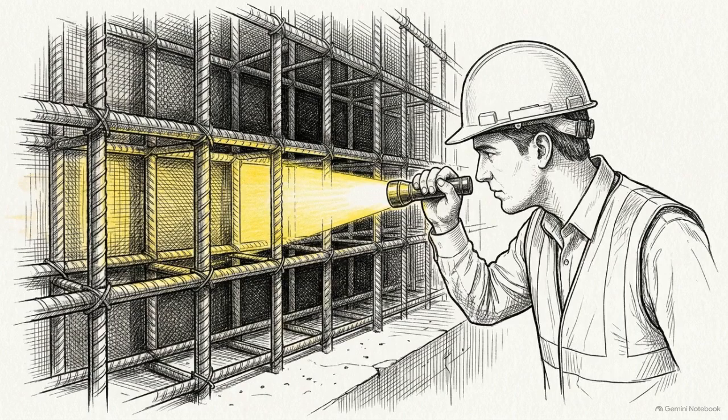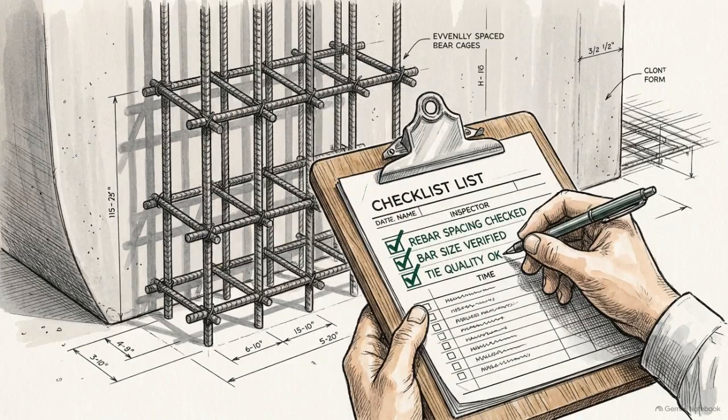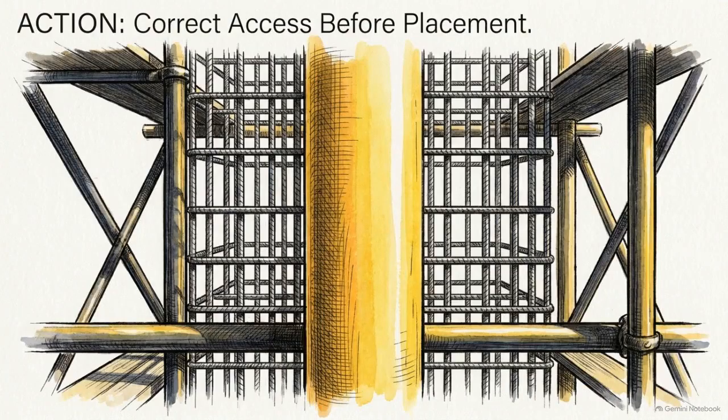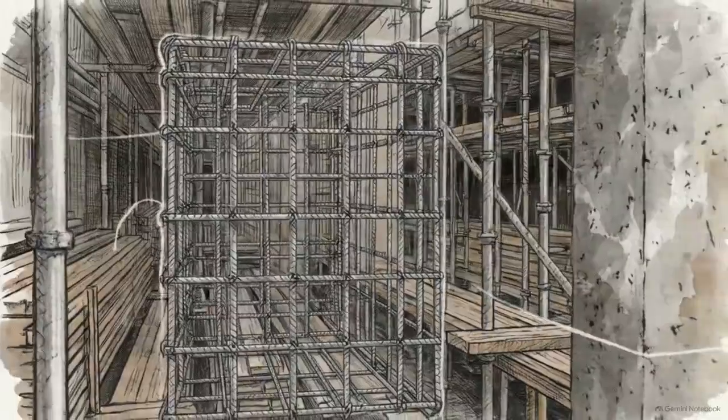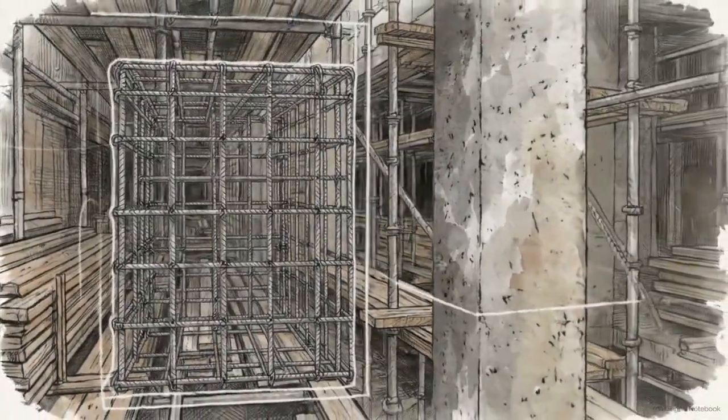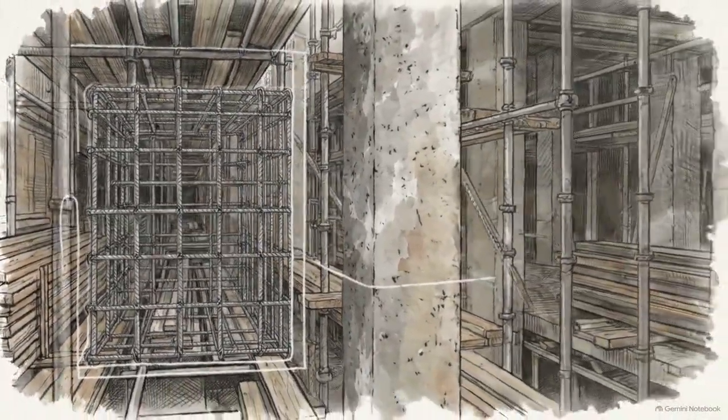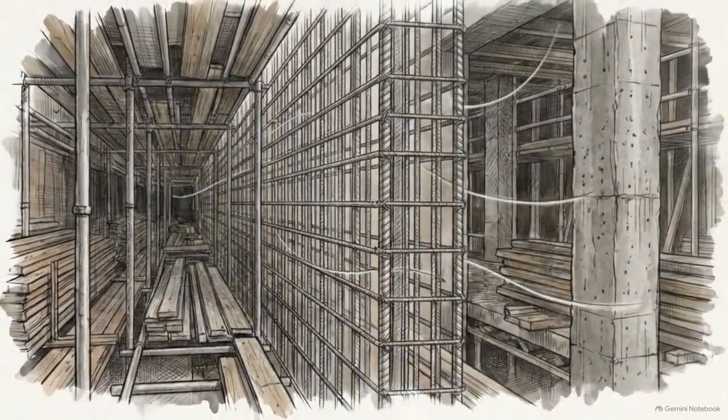Consider a field scenario where an inspector reviews a rebar cage and confirms that every bar is the correct size, properly located, and structurally compliant. However, a massive scaffold tube is positioned directly in front of the placement zone. Even though the steel is correct, this external obstruction prevents the nozzleman from maintaining a workable angle, rendering the cage unshootable. An inspector must always evaluate the entire physical placement environment. These external spatial constraints will inevitably dictate internal structural success.